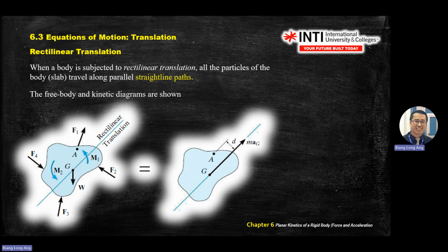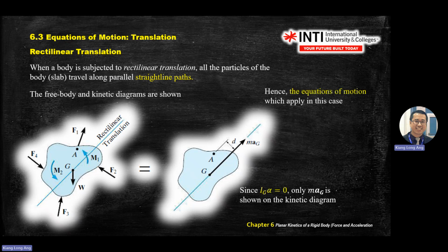Let's say you have all the force on the left-hand side, MA, you will see that there's a direction of the motion. You just need to find the axis and then find the right MaG. That's all. And then there's a D. D means there's a distance to a reference point there. This D is to tell you to calculate this one. There's nothing complex, although it looks like a lot of notation there.